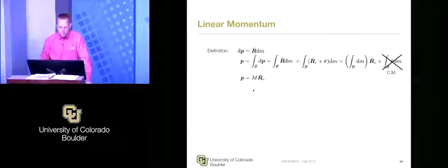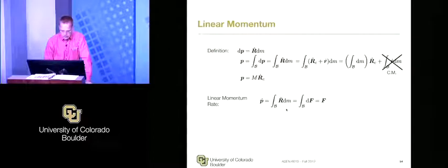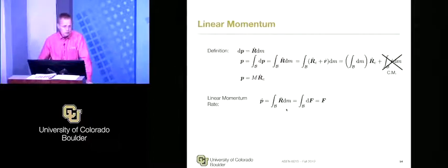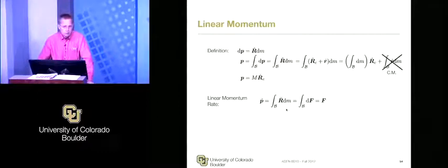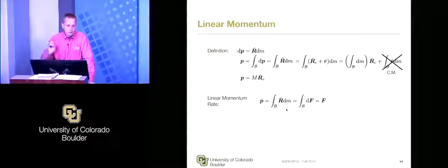Linear momentum has to satisfy these equations. Now, F equals ma is one way you can write this, but especially if you're doing the rocket equation, you don't do F equals ma directly. What is more fundamental is that the inertial derivative of linear momentum is equal to force. So the inertial derivative here ends up being, you add a dot, m RC dot.